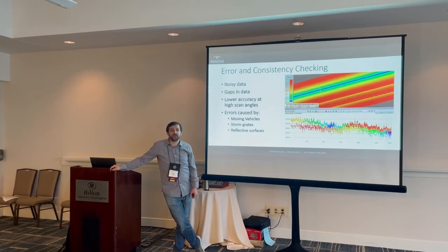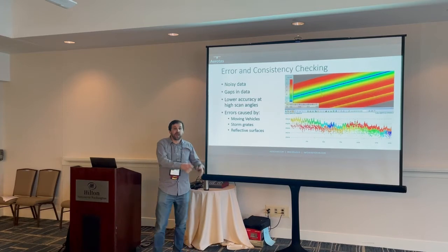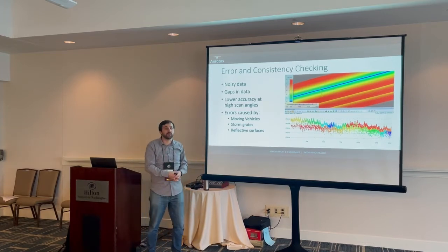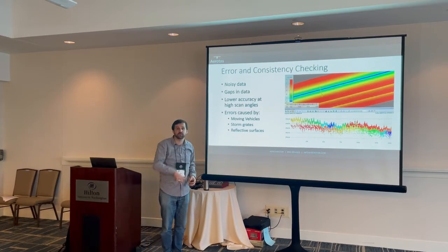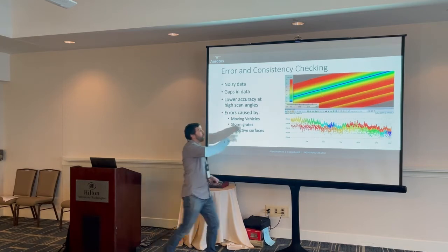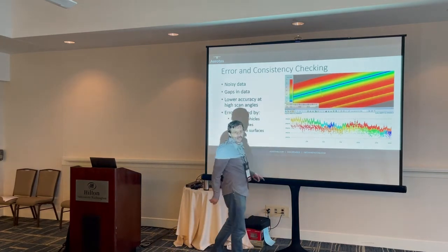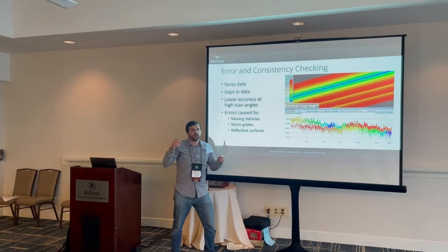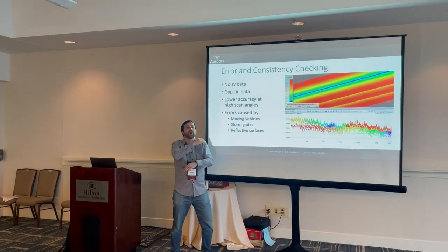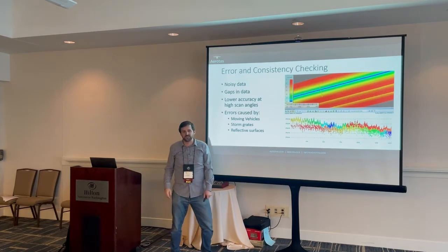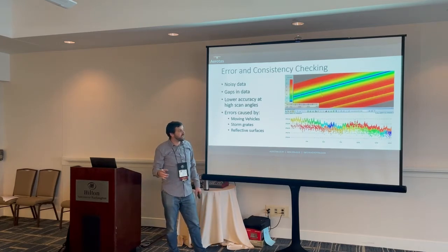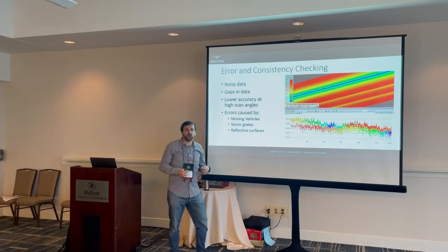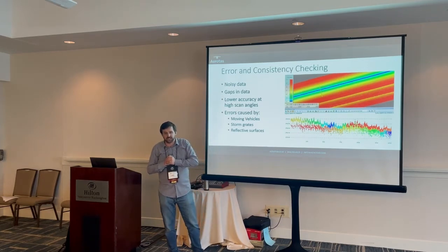Depends on the system, and that's part of the pre-processing step. So for the DJI-L1, the individual LAS file blocks are going to be based on each flight, effectively every time you change the battery. So one block might have 4, 5, or 6 flight lines. Some of the other systems that we've seen have every single flight line in its own block, so you can adjust those independently if you need to, or something like that. Typically, if you're using the local base station, having each individual flight as its own block is sufficient. You don't need to make other changes.